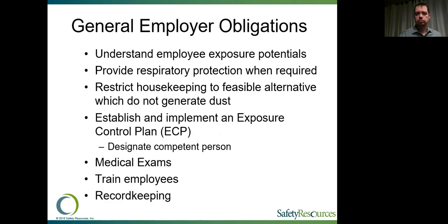requirements. So some basic employer obligations under this standard: you basically have to ensure that your employees understand what their exposures are, what the exposure potentials are, making sure that when necessary, respiratory protection is in place and it is being used properly, making sure that we are restricting housekeeping to whatever feasible alternative methods we can to ensure that we're not generating any dust during that process.